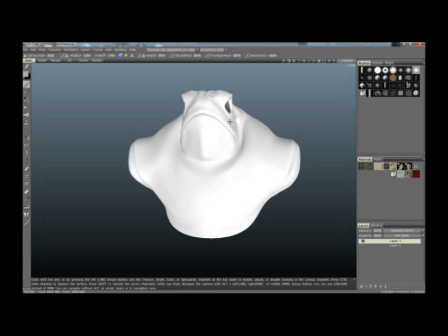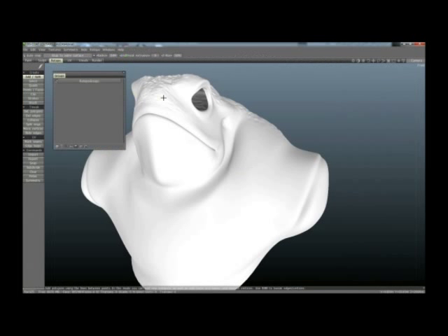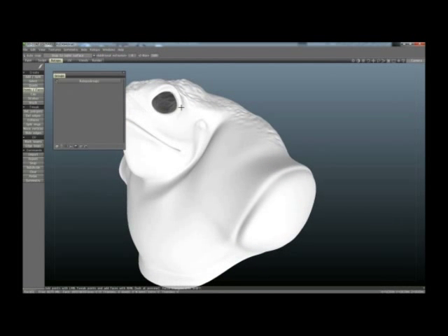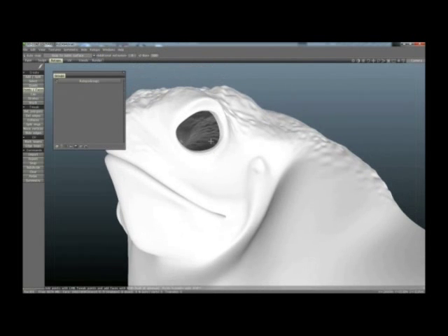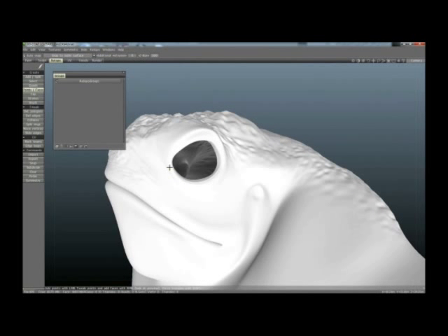Okay, so to start off, we're going to use the Point Faces tool. How this works is basically you put down the points of where you want to create your polygons by little dot markers. We're going to start around the eye, so I could just show you for example.